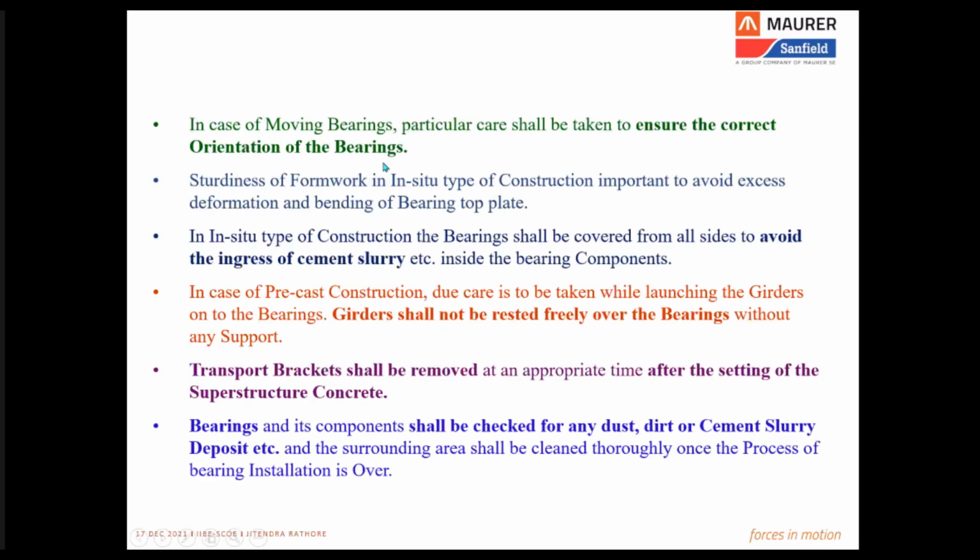In case of movable bearings, the orientation is important. I will also discuss this in detail. In case of precast construction, this is an important aspect, but it is to be ensured that the girders are not getting launched onto the bearings with an impact.